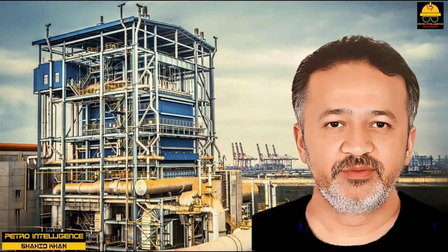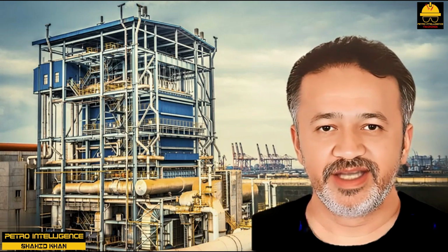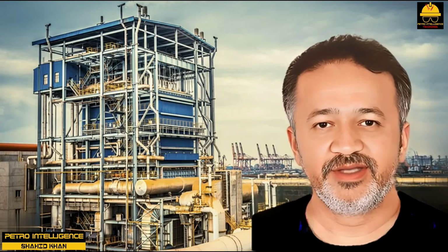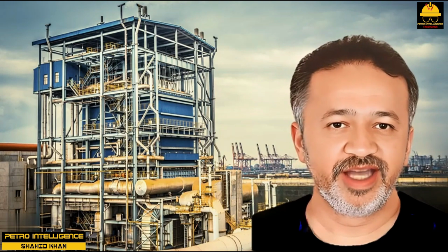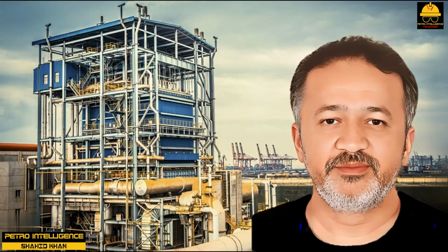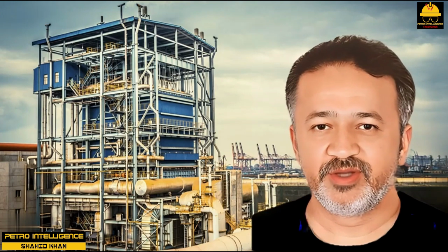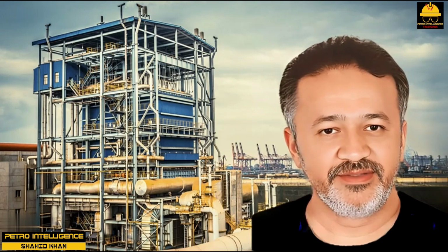Air cooler retrofit. In a used motor oil reprocessing facility, the vacuum tower precondenser consisted of a large fin-fan air cooler. Inlet conditions were 260 degrees Fahrenheit and 80 millimeters of mercury. Due to the contaminants in the used motor oil, this is a potentially very fouling service. Tube inserts, called turbulators, basically wire springs, were installed in the fin tubes by the manufacturer. The initial performance was reported by clients to be good.